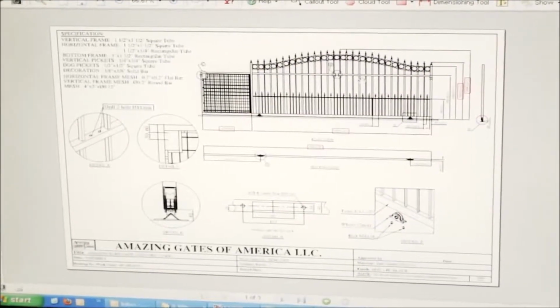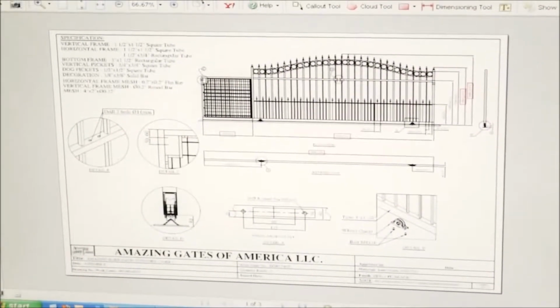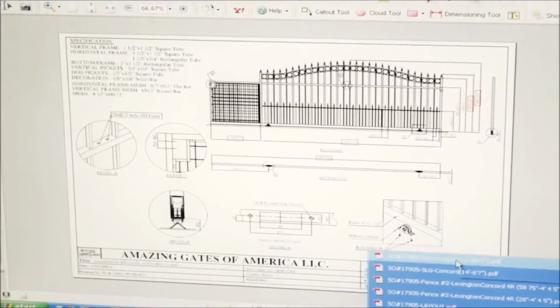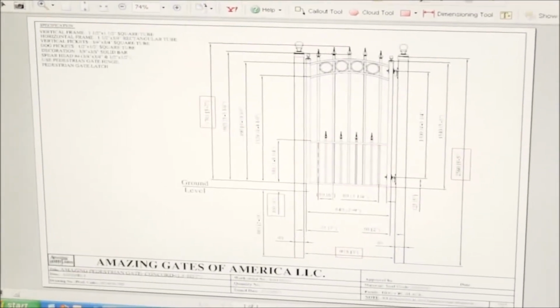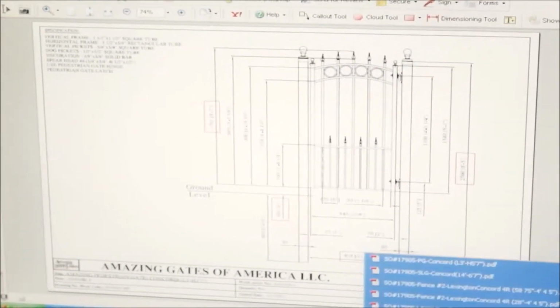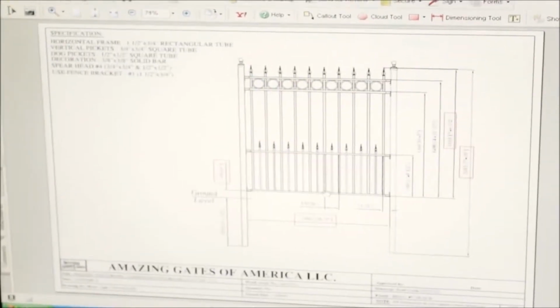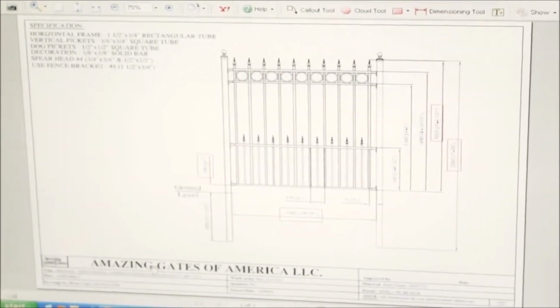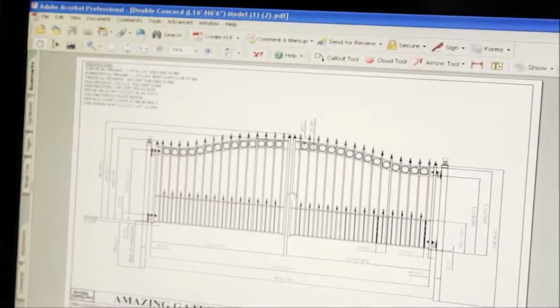As you can see in the production drawings, this is the assembly drawing for our production. The complete gate? Yeah, the complete gate assembly. And then each part is drawn in the different process of production. For example, this part here, part number 2, is cut, drilled, punched, and then that's the finalised product that goes into assembly. And these drawings are given to the actual fabricators out on the machine for you? Yes, each area of production has their own set of drawings for which part they're making. And then once all the parts are made, it goes through to the assembly side of things.